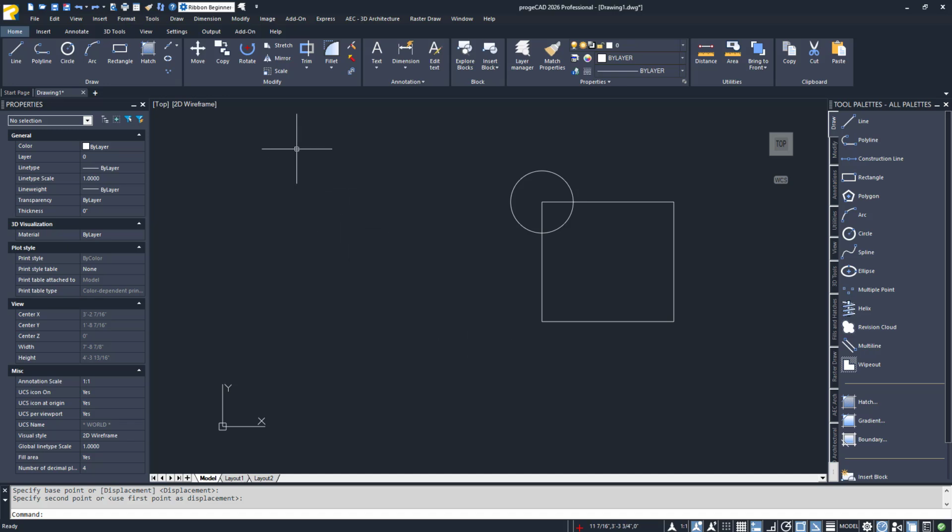Let's do another move. This time, let's move the circle from one corner to another by using E-snaps. I'll launch the command, use a pick box to select my circle, and press Enter. My start point will be the corner of the rectangle, but I could also use the center of the circle. As I begin dragging the circle to the opposite corner, make note of the dashed yellow rubber band line indicating the path and a preview of the entity being copied. I'll acquire the endpoint of the rectangle, select it, and the circle will move and the command ends.